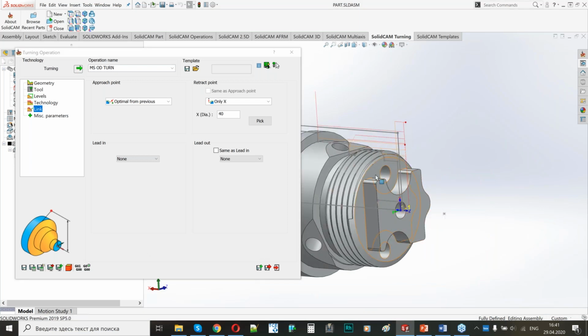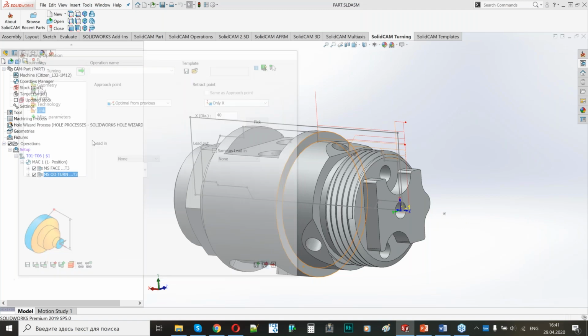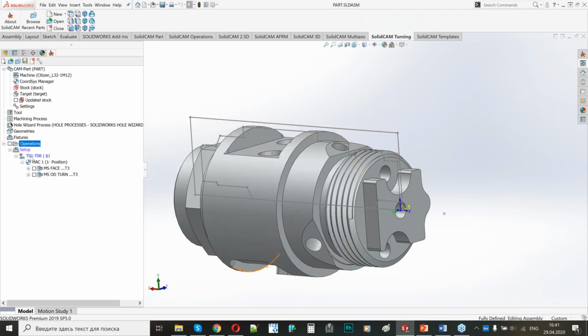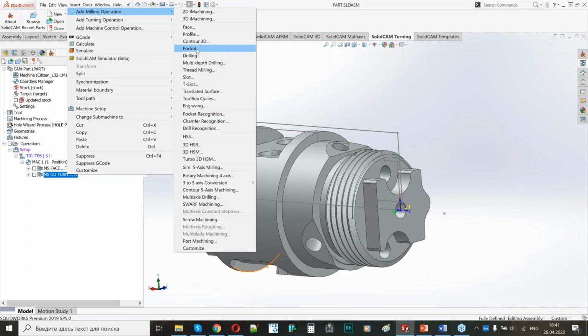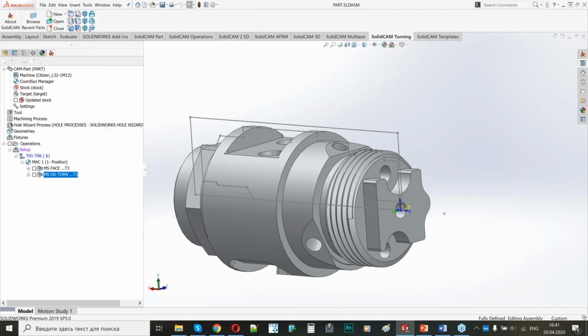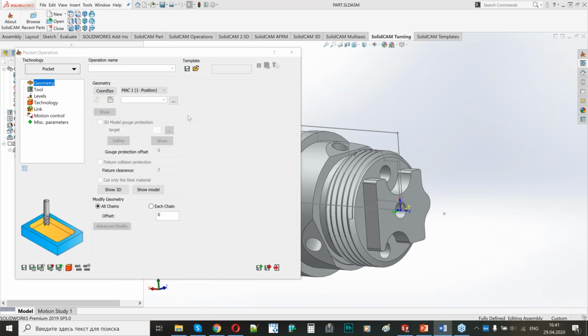And now I'm gonna apply the milling operations on a face. I will use the open pocket, and then I will perform the drilling operations on a face. And here I can see what tool block is responsible for those operations. It is very convenient. I will apply milling and I will apply pocket. I will call this face mill operation.